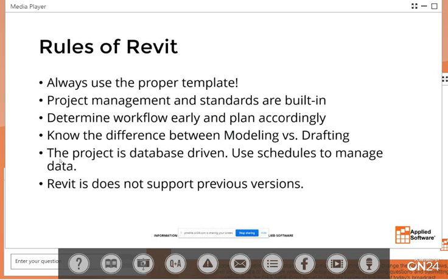So you can't do a save as to an older version. This is why we asked the poll question of the version of Revit that you're in. If you're moving into Revit and you start customizing everything and creating new title blocks and new text styles, and you're doing it all in 2023, and you've had 3 days of work developing standards, and on Monday you get a job that's in 2020 Revit, well, all those standards you developed in 2023, you cannot use in 2020.